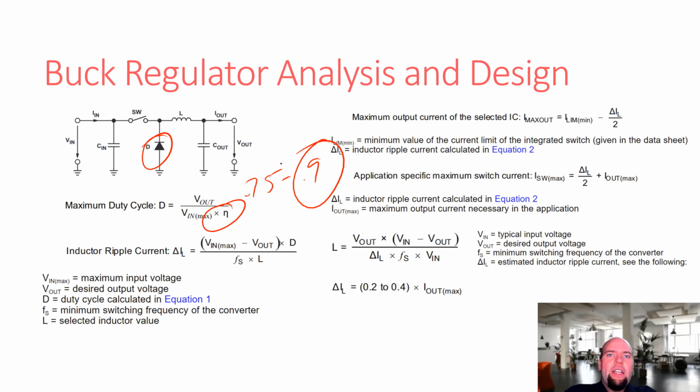The problem is it's a bit of a chicken and the egg. Your efficiency is going to be based on your design setup, but you need to know the efficiency to do the design setup. So one thing they tend to do is show application curves, which help you ballpark what your efficiency is going to be before you even start your regulator design. I show one of those in a later slide. I don't know why I don't have it on this slide, but I don't.